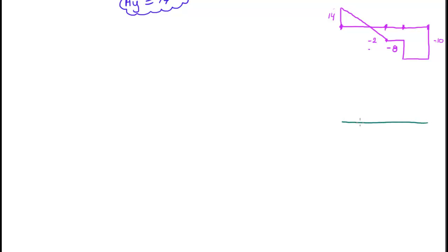Well, there is a theory behind it, no doubt about that, but just to do it quickly in an exam, the way you think about the moment diagram is that all the values of the moment diagram are simply the areas underneath the shear diagram. So if I have a way of calculating this area as a positive area, and then calculate this area, and then that, and then that, I'll end up having the whole bending moment diagram.